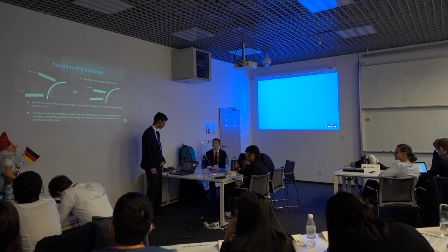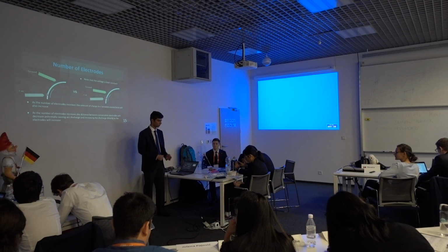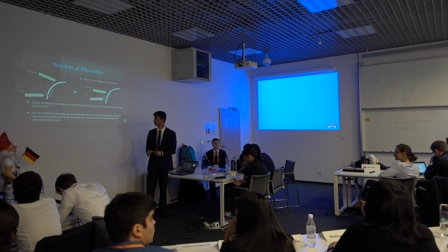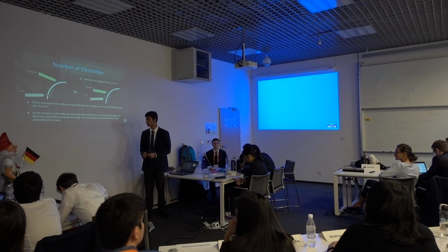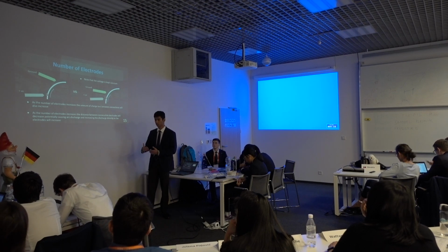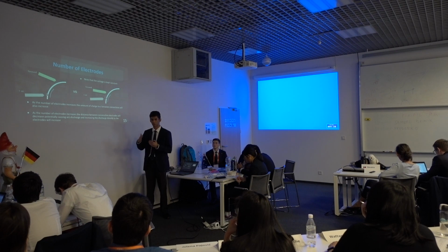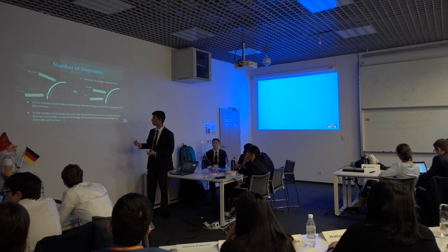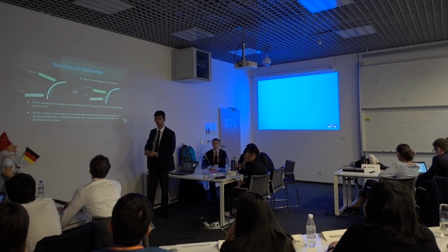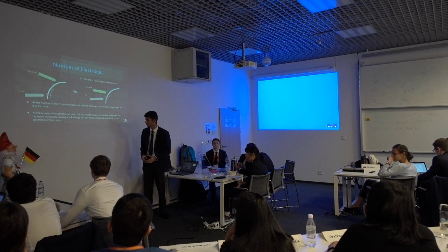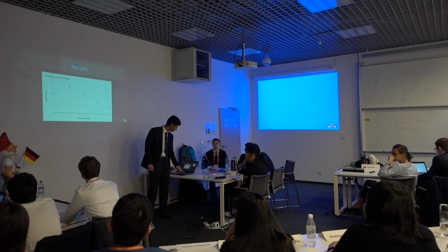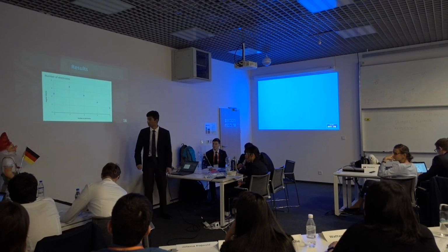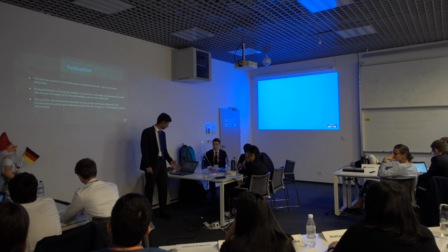To investigate the number of electrodes, it was hypothesized that as the number of electrodes increases, the amount of charge lost between the connections will also increase. And as the number of electrodes increases, the distance between consecutive electrodes will reduce, and this will encourage more dipolar discharge, which is not good for the actual spinning of the cylinder. Our experimental results were in conjunction with that, except for the discrepancy at 2 electrodes.